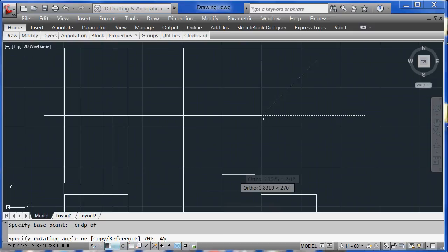line, and I want to right click. I'm sorry. I'm going to type the command line, shift, and I want to go to the center of this, and then let's turn the orthogonal back on by F8. I go here, okay, and then let me do it again, line, shift, and then right click simultaneously. We'll go to the center of the circle, we'll go there, and then all I need to do is,